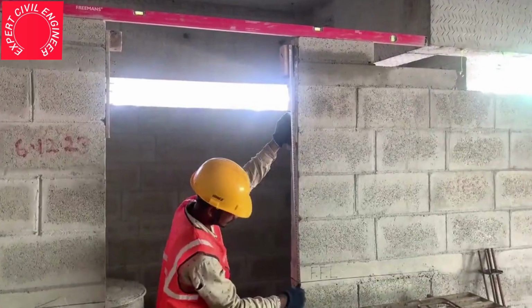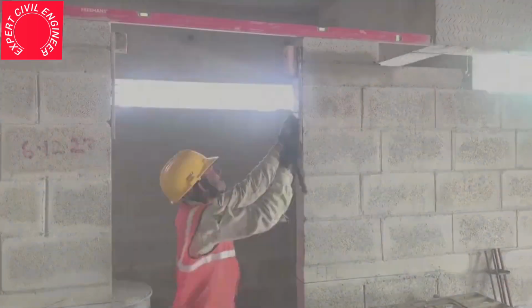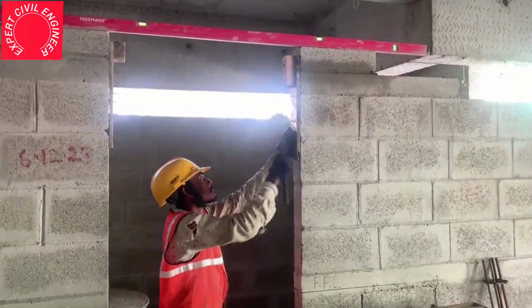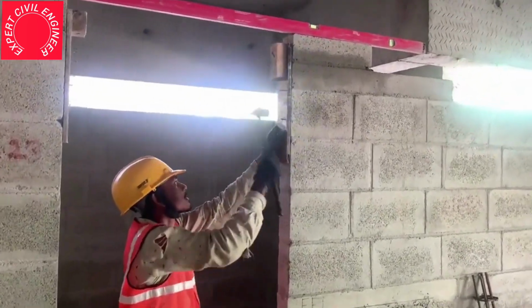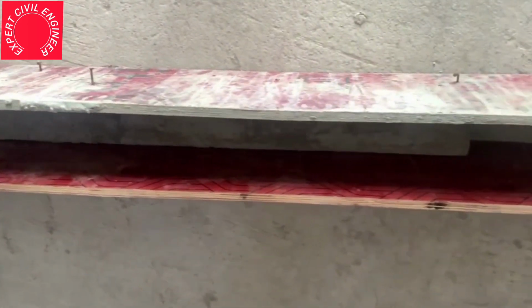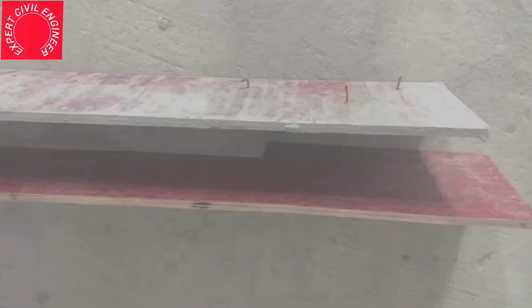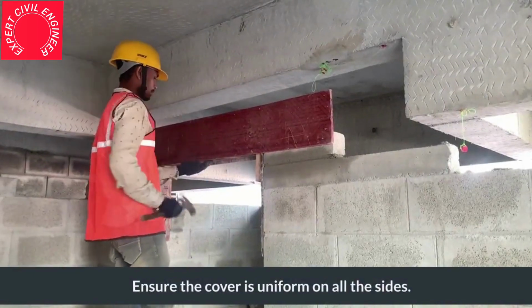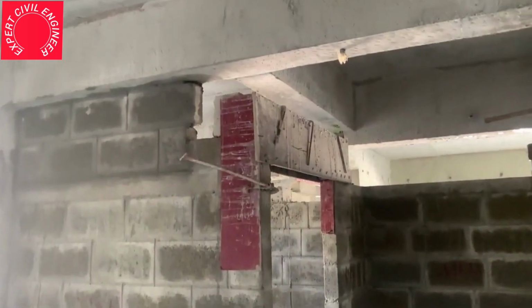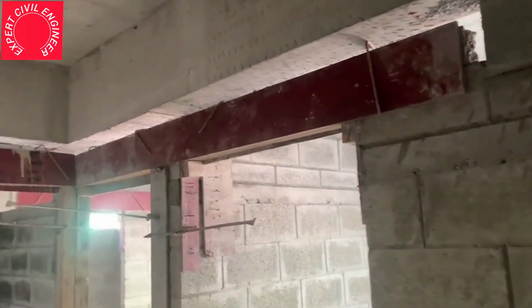Prepare the ready-made formwork box and ensure that the bottom of the lintel level is cross-verified. Fix the bottom support securely before placing the side boards. Place the fabricated reinforcement accordingly in the ready-made formwork box. After thorough checking by the engineer in charge, the approved grade of concrete is to be poured and ensure proper compaction for better finish.